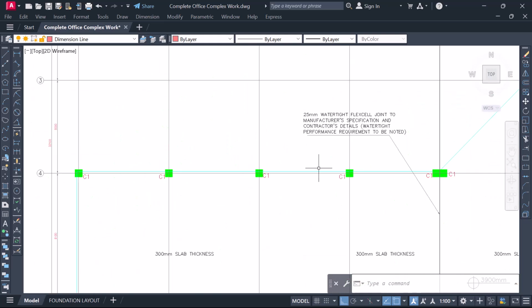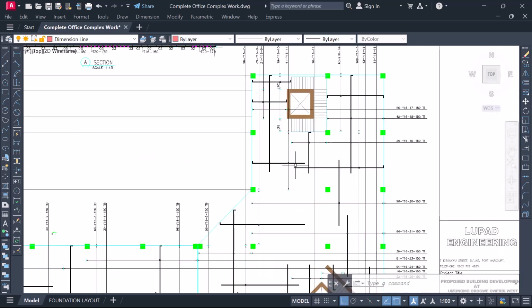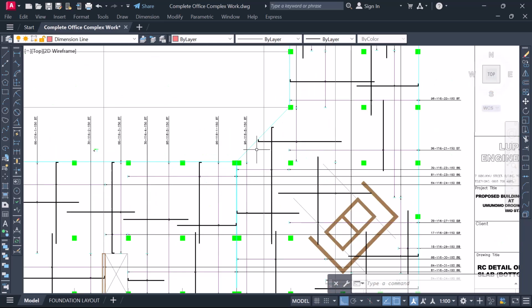Yes, your design report was okay, your design was okay, but the detailing is wrong. So for a good and effective structural design, any design at all, what you did on your design must reflect exactly what you did on detailing. Right? So good design, good detailing, the structure will stand. Good design, poor detailing, collapse of the structure will happen. Poor design, good detailing will cause collapse of the structure. But good design and good detailing, perfect. You have a wonderful structure.